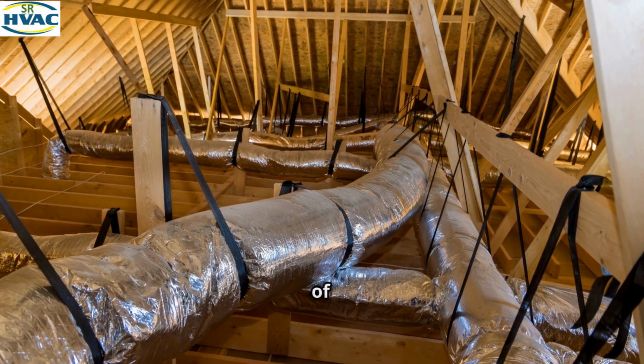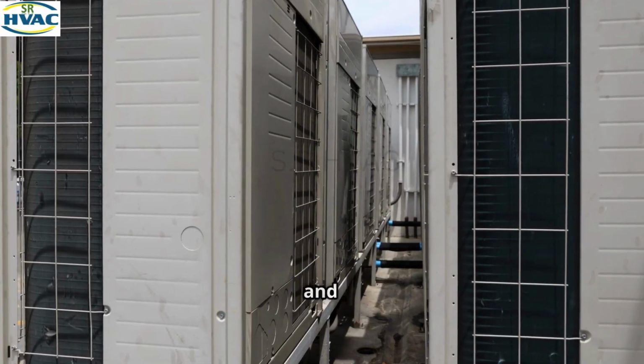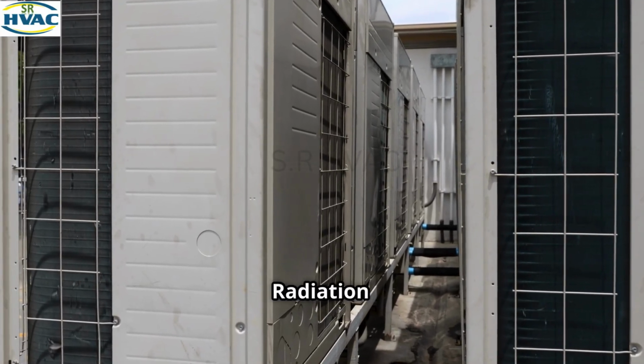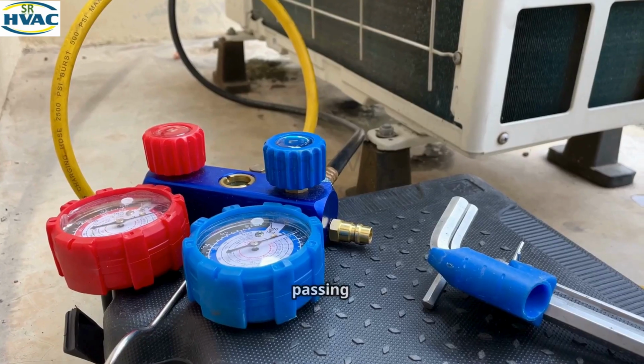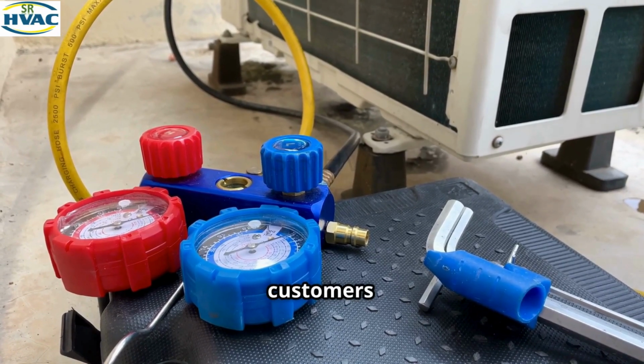Quick self-test. What kind of heat transfer happens in a duct blowing cool air? Convection. Between a warm compressor and a mounting bracket? Conduction. From the sun onto a rooftop AC unit? Radiation. Understanding these isn't just about passing tests, it's about diagnosing faster, saving energy, and serving customers better.